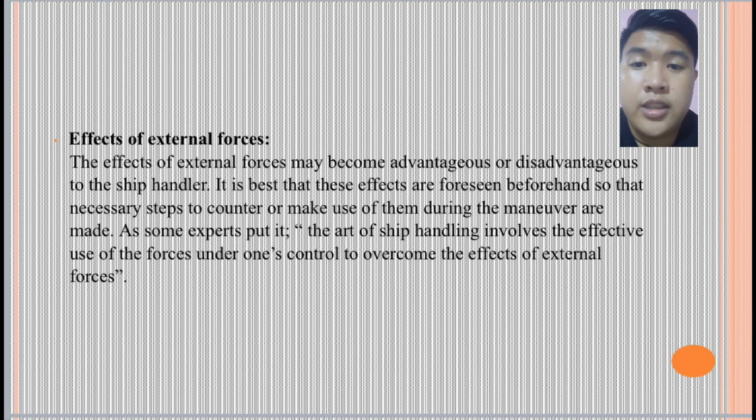When there is wind blowing on one side of a high-sided ship moving ahead, she will not move along the line of her intended course, but rather drift towards the lee side of the ship.